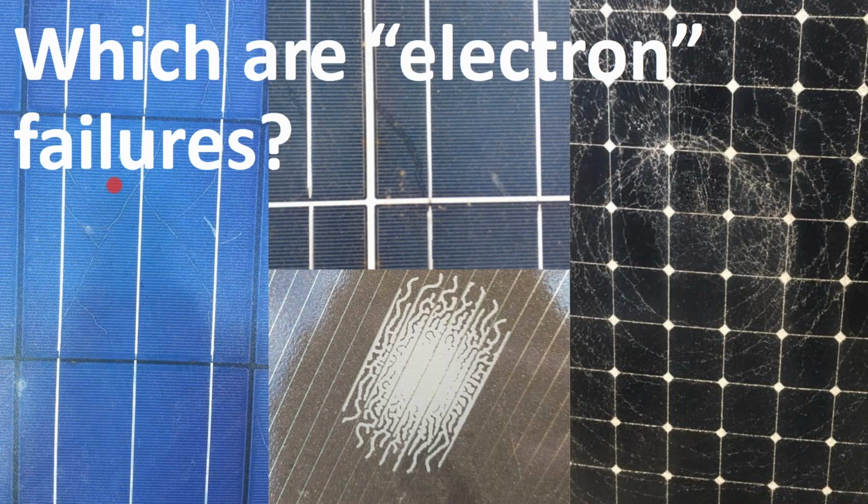So it's a very difficult, poorly understood fault in the solar industry, that sometimes doesn't matter to the end user at all, because it doesn't trigger the warranty, because it doesn't trigger any performance loss. But if you get a fault occurring all the way across a cell and then isolating this silicon from getting to where the current flows into, you would lose that much voltage off of your cell, and that could be problematic by basically ripping a corner off of every solar panel tied into that circuit. At any rate, something like this would even be dramatic, but not enough to trigger even a step down warranty.